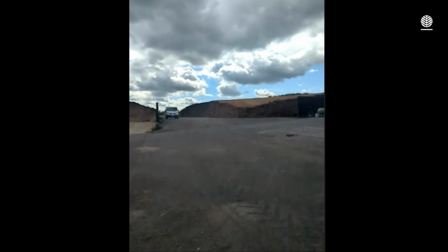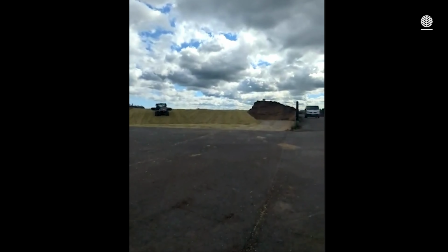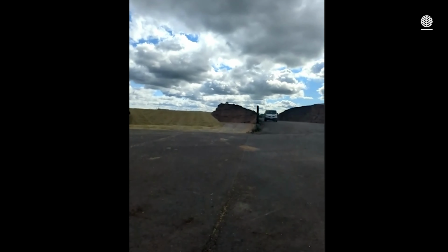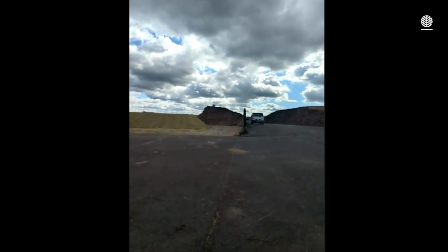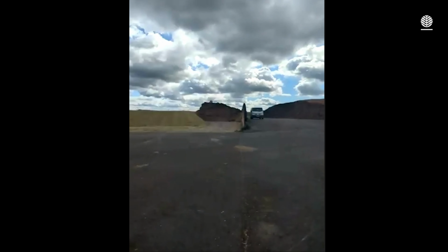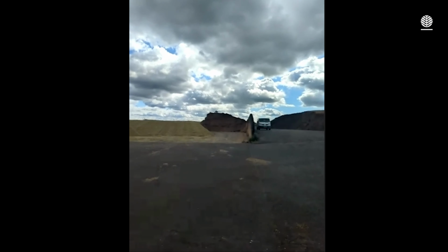Okay, so we can see the drive-in silo. They're huge. It's because feedstock is around 60 to 70 tons per day, and we can yield around 150 to 220 cubic meter of biogas per ton of feedstock. It depends on dry matter content and the quality.